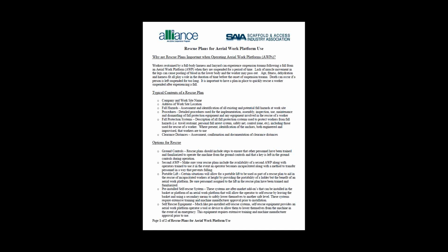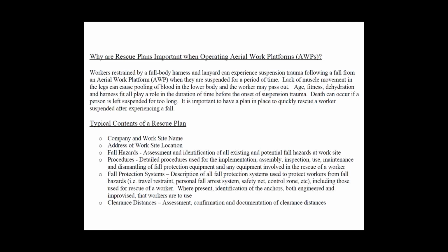Now we need to look at rescue plans. Again, regulated by 502, if we're wearing fall arrest, we need to have a rescue plan in place. And here's a 2-page document that goes over a rescue plan. And I'm going to try, and I don't know if it's uploading. I have 98%, so I'm going to go ahead and say, let's kind of drill down to this document.